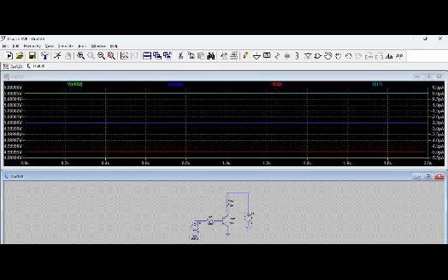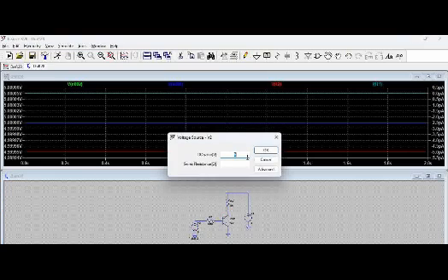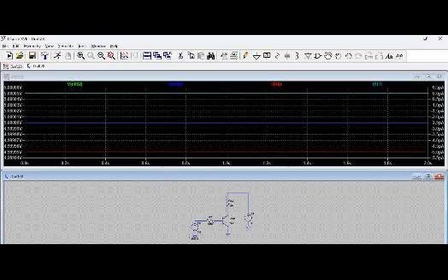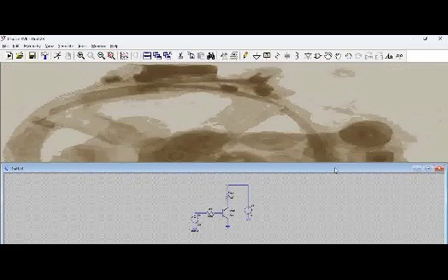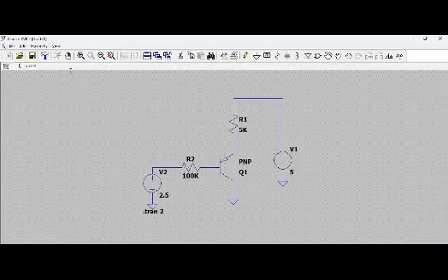Now, as we discussed in the theoretical part, if you reduce the voltage that is being applied to the base, you are actually trying to turn on this particular junction, and in that case, you will see the current flowing. So now, let us make this some 2.5 volts. Let us close this and run this.